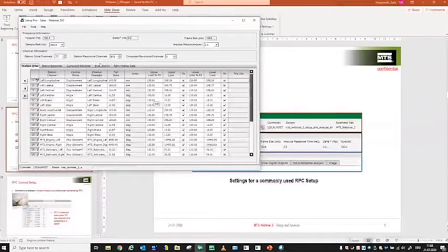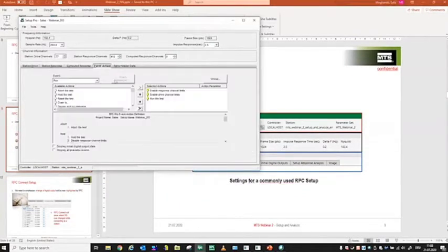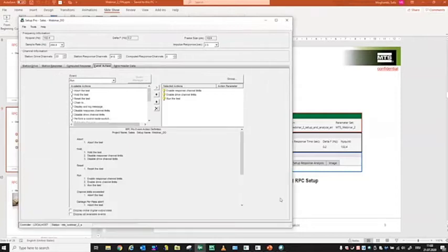So once the setup is connected, as you can see here, we have this little tab called Event Actions. And what most of our customers do is they hop into that and say, okay, for the run section, for example, if we want to iterate a brake event, we are going to use these event actions to clamp the brakes and unclamp the brakes.